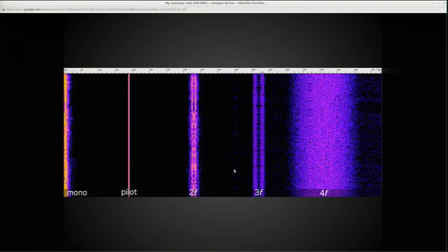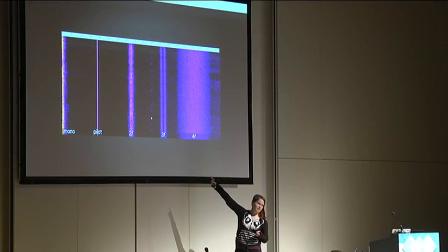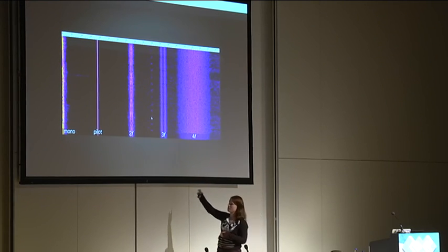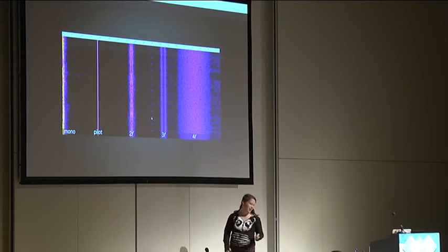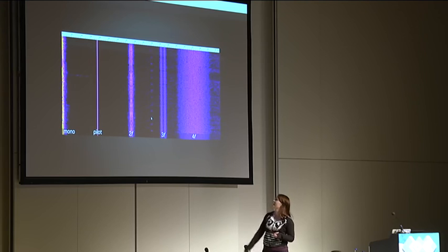On the left, there's the audio, and there's the obnoxious tone you just heard. Here we have a stereo separation signal that tells the relation of the left channel to the right channel. Here's RDS, where it actually should be, but for some reason it was aliased to around the pilot zone in my older radio.